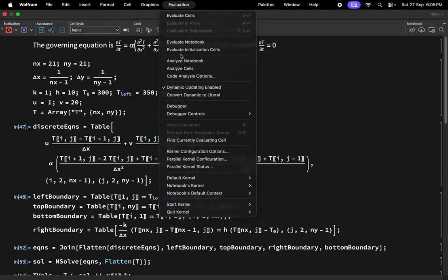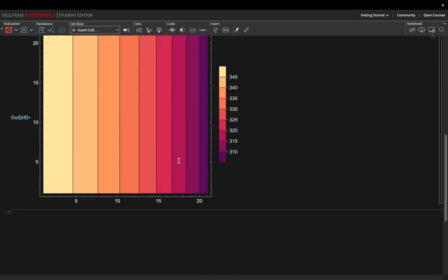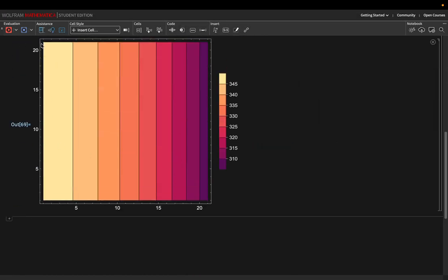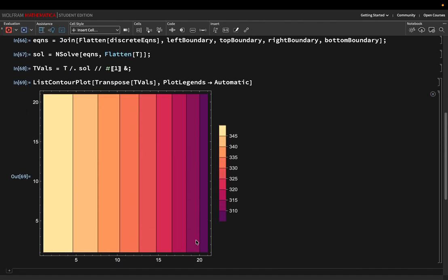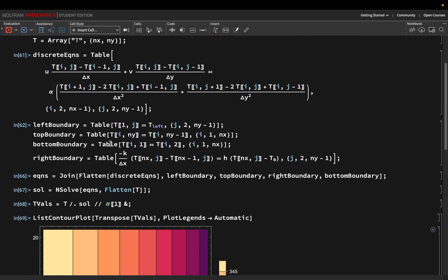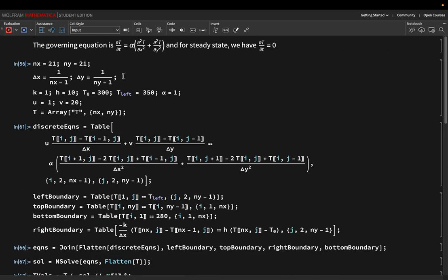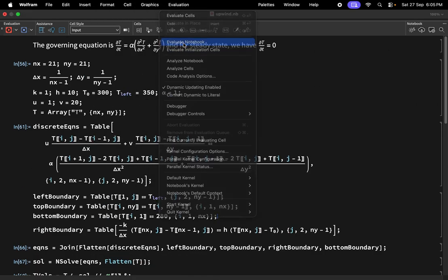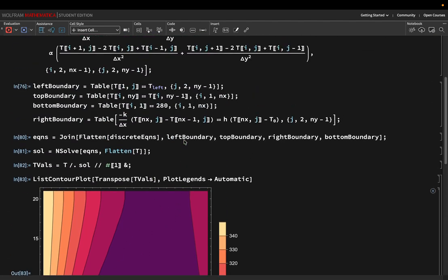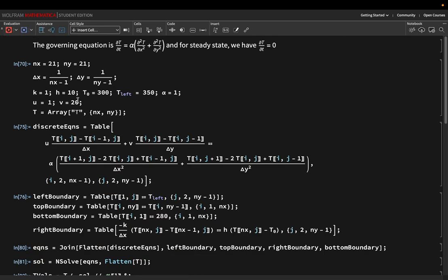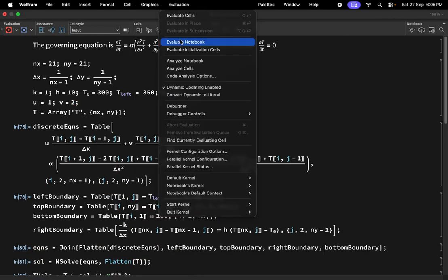And that is essentially because I have prescribed the temperature only along this. So for example, at the bottom boundary, if I have a cooler air coming from the bottom, how would I change it? The bottom boundary previously was adiabatic, so I kept Ti1 equal to Ti2. But instead of Ti2, let's say it is constant at, say, 280 Kelvin. So this is basically trying to cool the room. Then you would expect something like this. There will be a cold blow of air. Of course, there is no gravity here, which I should have included, which you can try later. But let's keep a smaller velocity so you can see it more clearly.